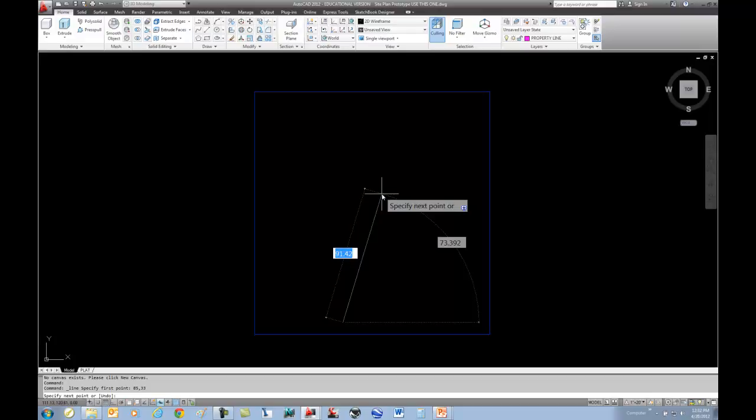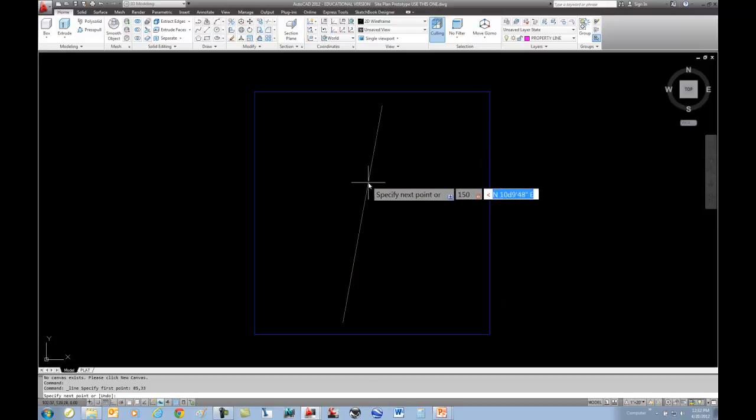So as you're drawing your first property line, you're going to enter 150 for the distance, just the number, no apostrophe. Then press the less than sign, which is shift less than, that's the symbol above the comma. And what you want to do is enter in your bearing. So that's going to be either upper or lowercase, doesn't matter, but it'll be N 00 for the value of the degrees.